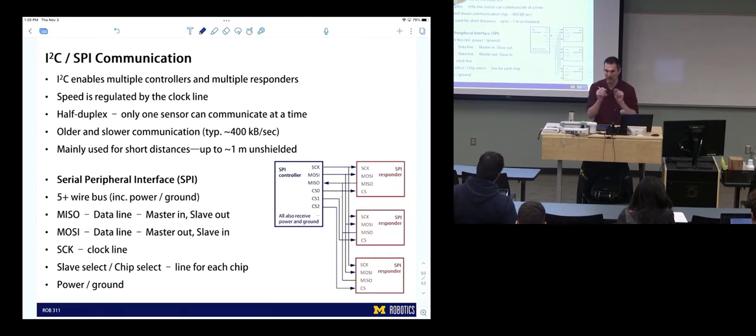A lot of it depends on the length of your wires. Why does the length of the wires matter? Farther for the data to go. But why does that matter? Why is that a bad thing? What happens when the wires are too long? More resistance. More resistance, yeah. More capacitance is actually the issue. More capacitance, so it slows the rise of the pulses.